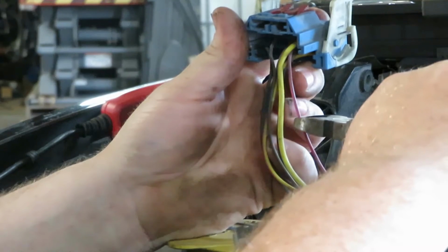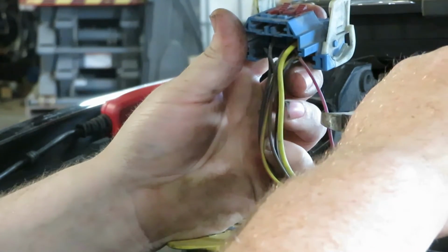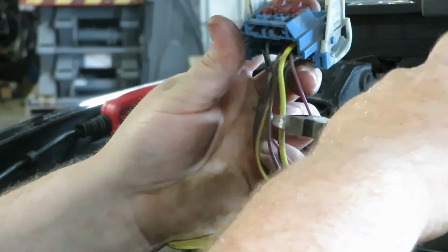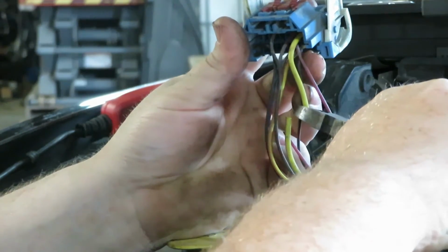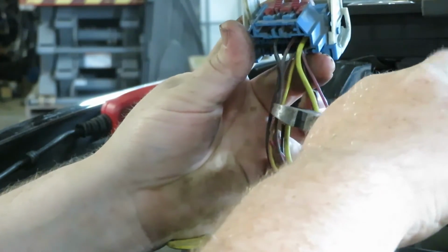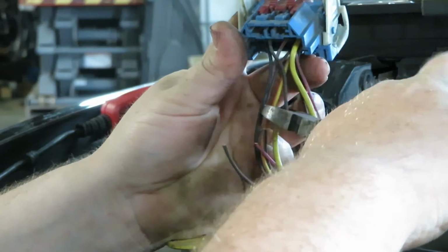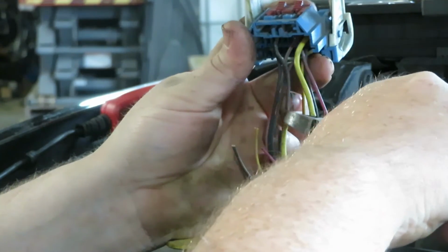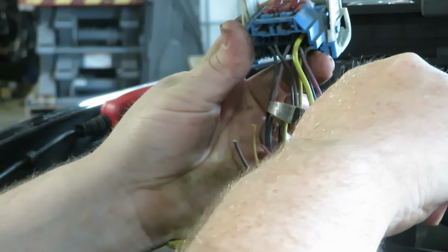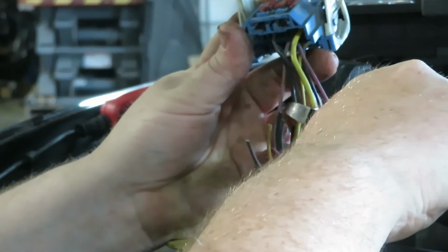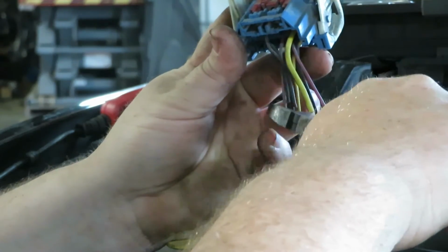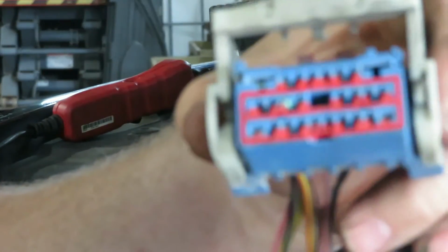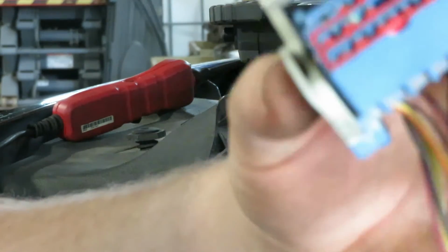You take a connector and just cut them off all at about the same length, leaving enough room to get your shrink wrap and everything in there, and enough room so that you can solder it. So there we go, we got our connector off. Now we'll take it over to the bench, find out what size wires go where, and put them in.